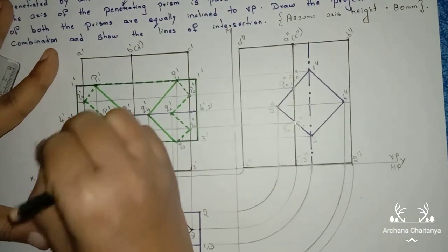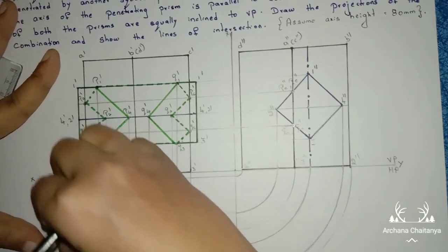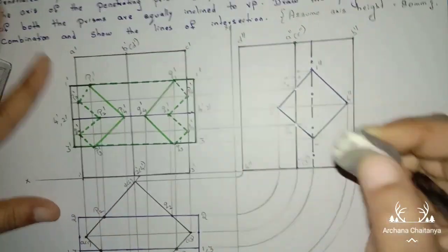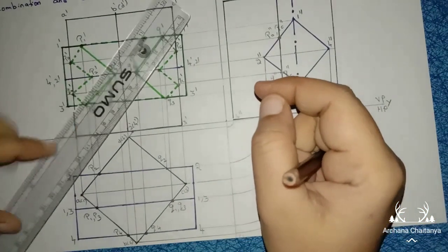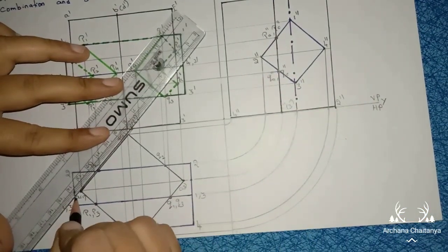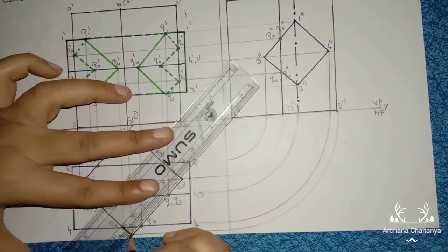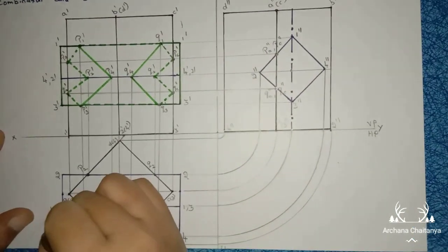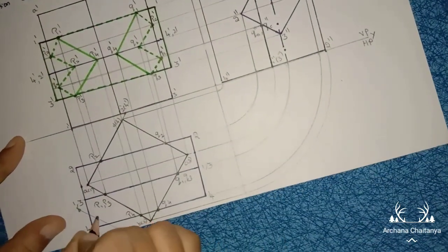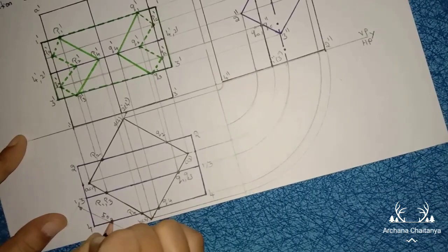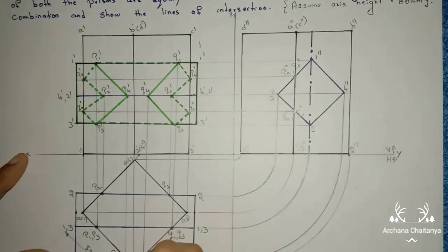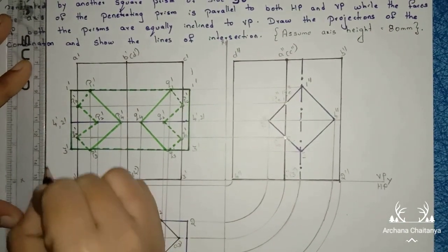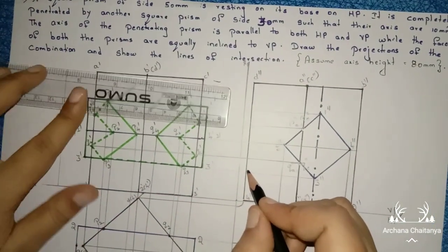Okay, we will mark here only. You should not mark the dimensions in the diagram, so just extend this outside here. I am not having place, just extend this outside and write down here length of this square is here 50 mm. Draw the dimensional line properly and write down here this is 50 mm. And here axis height 80 mm, take the axis height 80 mm.